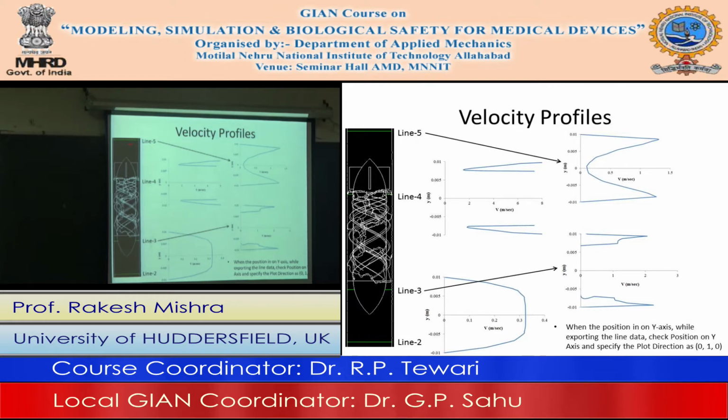Okay? So that is the velocity profile at this particular point. Locally, this type of information you can get only from CFD or from very sophisticated measurements that you can take. Otherwise, this type of information will not be available to you. So now, if you just plot the gradient of these, okay, just plot the gradient of this and you can see the shear stress distribution everywhere. So everywhere you can calculate how much shear stress is acting on blood, and what effect it will have on the blood properties. Okay, making sense? Any questions on this?